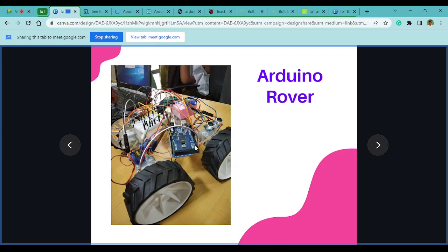You can see this is the module, and we connected it with a lot of sensors. This sensor looking like an eye, right, is an ultrasonic sensor. This is used to calculate the distance between objects. Based on that we can control the way this rover moves. I think we have four simple motors for the wheels. And these blue boxes are servos. A servo lets us control the small movement of small objects. This was supposed to be a hydraulic arm, connected with this one.